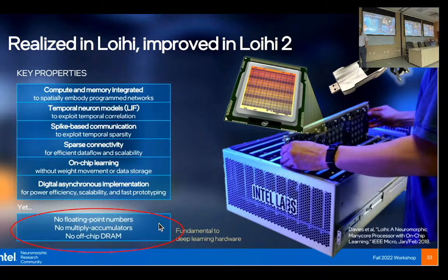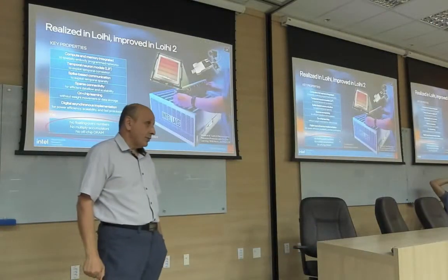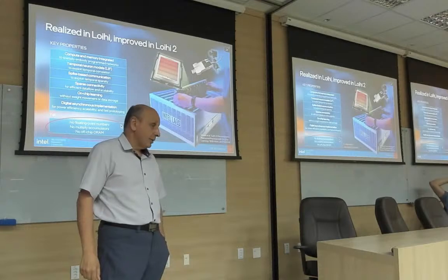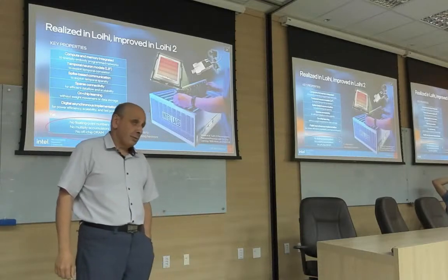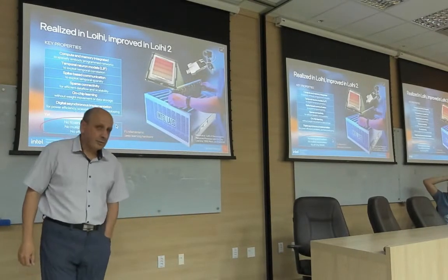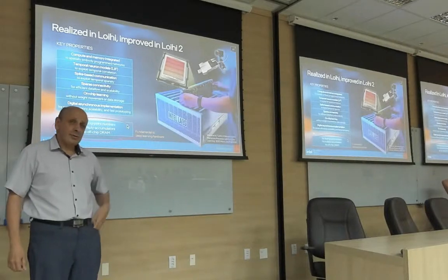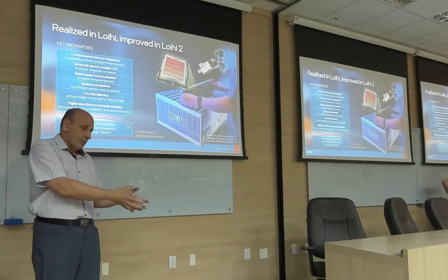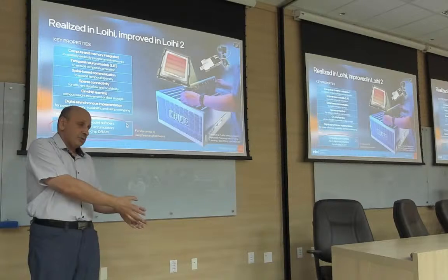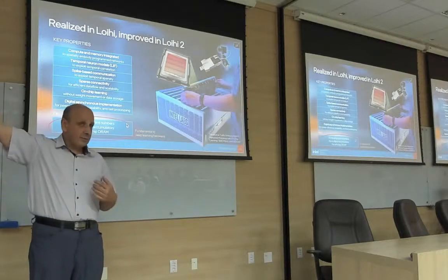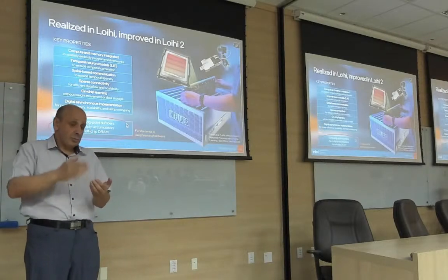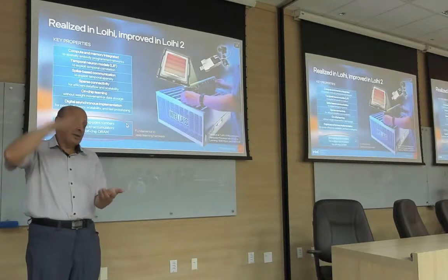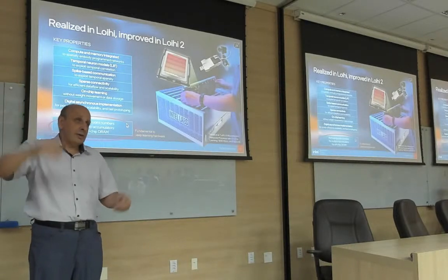Some of the highlights, difficulties with Loihi. To stick to that energy budget, they stuck with fixed point arithmetic rather than floating point, which for us is no big deal. Floating point is necessary if your models need to do something from subatomic particles to galaxies, but in neural computation we know we're going from the reset to the threshold, so that's not a big deal.